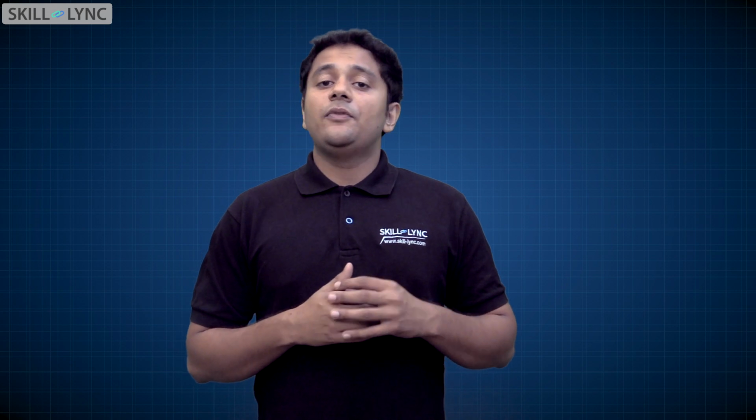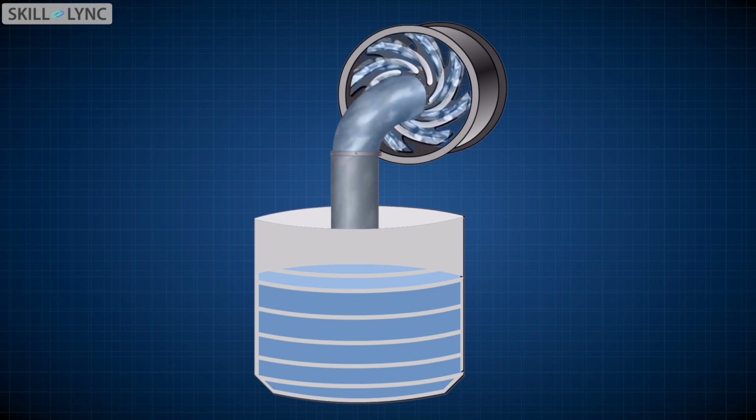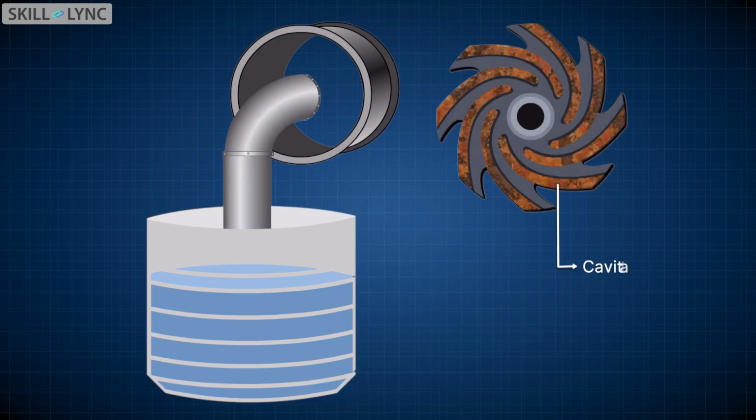Cavitation can affect your equipment in several ways. When fuel cavitates in a nozzle, it affects the fuel mass flow rate. This can further affect the combustion and emission performance. In the HVAC or turbo-machinery world, it is important to study cavitation in rotating devices. For example, in centrifugal pumps, the impeller rotates at a very high speed, due to which a low pressure zone is created. This can lead to cavitation.